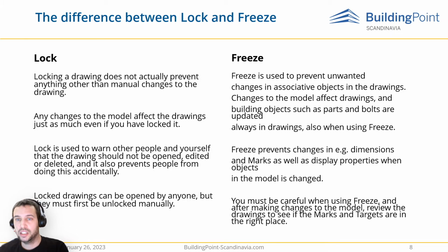Freeze, on the other hand, is used to prevent unwanted changes in associative objects in drawings. Changes to the model affect the drawing. Building objects such as parts, bolts, etc. are updated in the drawing. So adding extra functionalities, extra parts, bolts to your assembly will be shown on the drawing.